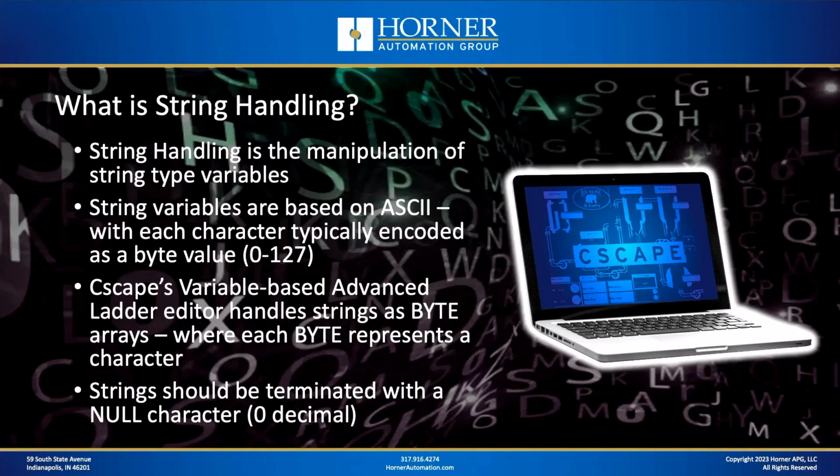Now, generally when you're working with strings, whether you're talking Horner type programming or just something off the shelf, IEC related, for example, generally strings should be terminated with what's called a null character, which is an ASCII character that has an ASCII code of 0 decimal.